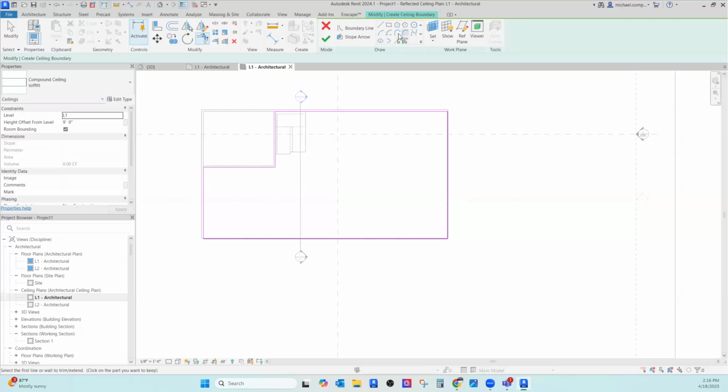The way I like to do curves is using the fillet tool. If I just drew a line for a 45-degree angle, this is a design thing, you can do whatever you want. If you go 1, 2, 3, 4 over, there's this fillet arc. So I choose that, and then I click the segment I want to keep and the other segment I want to keep, and I can drag out. Oh, it went the wrong direction for some reason. Let me trim this up. I'm going to trim these up so I don't get weirdness going on.